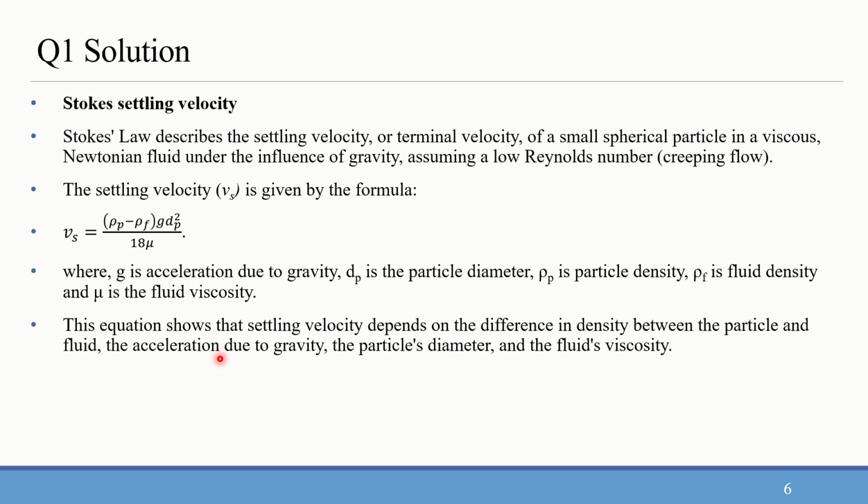So when we say it is Stokes regime, it is when there are high viscous effects or low Reynolds number flow. That time we call it a Stokes regime. So the formula is given over here. You can also do a force balance and get it, but the easy way is remembering the formula, because we will be repeatedly using this formula everywhere whenever we are talking about fluid particle mechanics. So better to remember it now only.